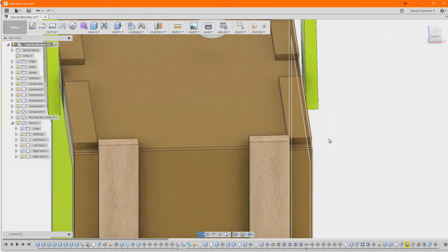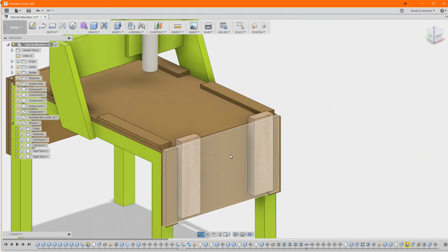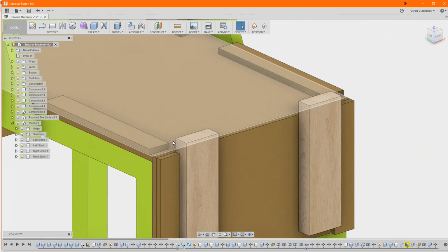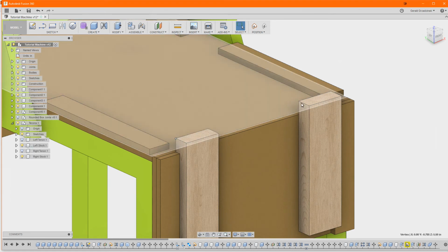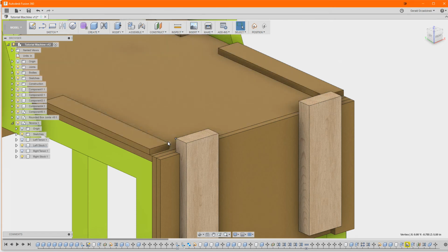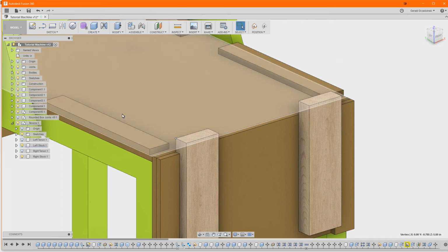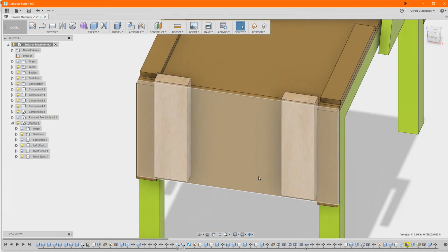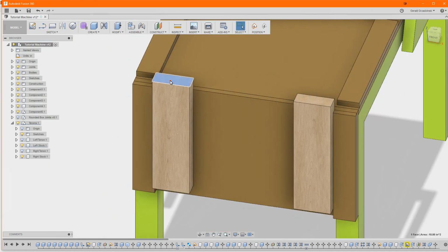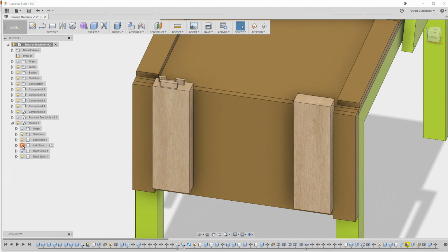Now if this is your X-axis, then your origin is going to be over here. X0, Y0, X plus moving off to the right, Y plus moving away from you, back to the back. So basically you're going to set your Z0 at the top, and then you're going to machine them, and you're going to end up with tenons, left hand, right hand, opposite.